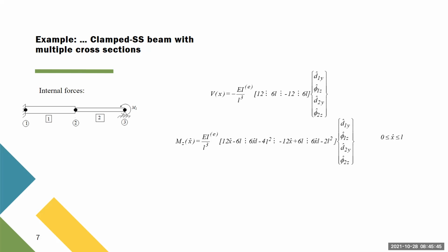That's for the internal forces. Remember, shear force for every element is constant because of the assumption. Bending moment is linearly varying in every element. So these are the solutions. In this case, since we apply external forces only at the joints, or the other way, we have one joint in every point where we have an external force, the solution is exact.